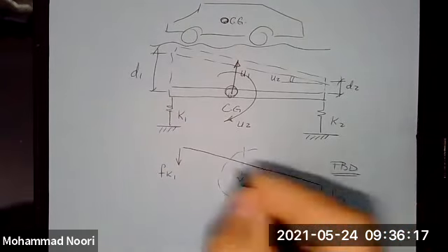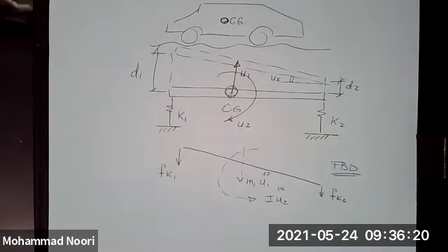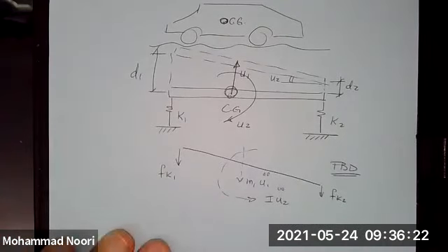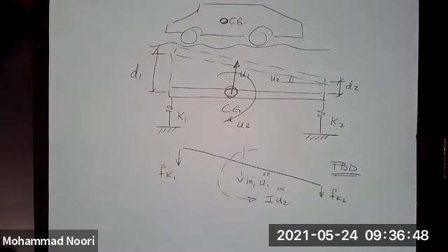You may say that this is such a simplistic model for a car, but believe me, this is a very basic model. It is the first fundamental model used even in some complicated analyses where you want to find simply the first two frequencies, and for instance, make sure the engine operation is not within that range. It is a model that is used even in some complex analyses.